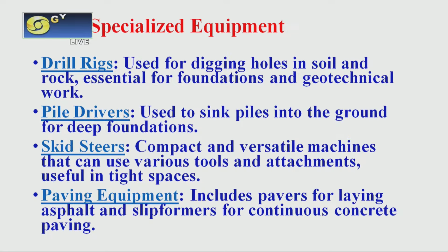Then there is other specialized equipment also, like drill rigs, which are used for digging holes in the soil and rock, and are essential for foundation and geotechnical work, for creating foundations of the building, or when some geotechnical investigation is to be done. These drill rigs are used to take out samples by digging holes in the soil.